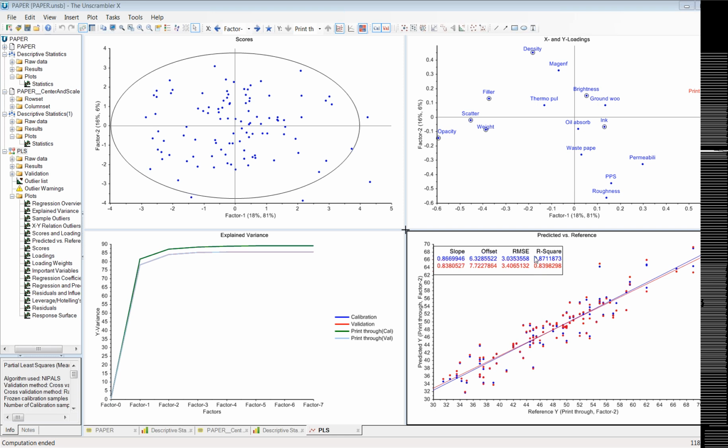You also want to look at your R-squared. That's how well the data fits the line. Depending on your process, over 80-85% is pretty good. Some places you need 95-99%. Again, it depends on your particular application.